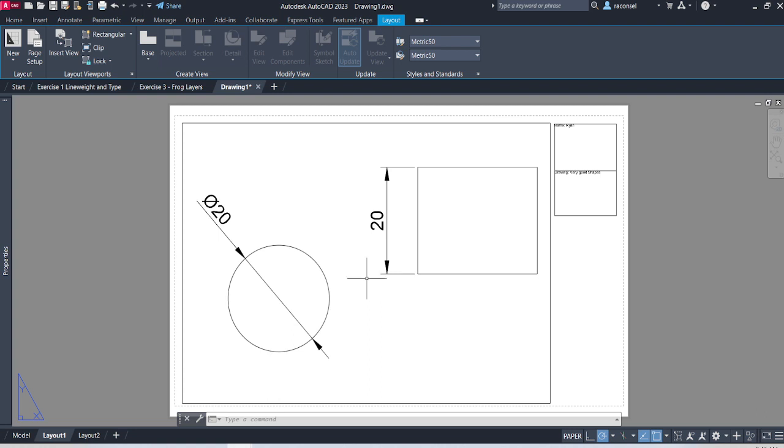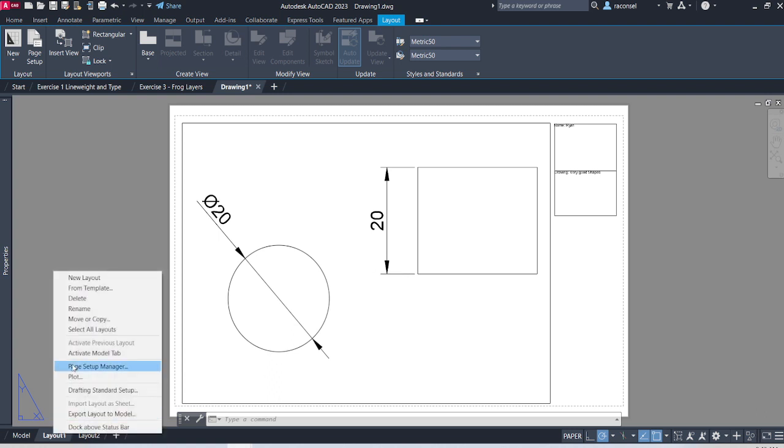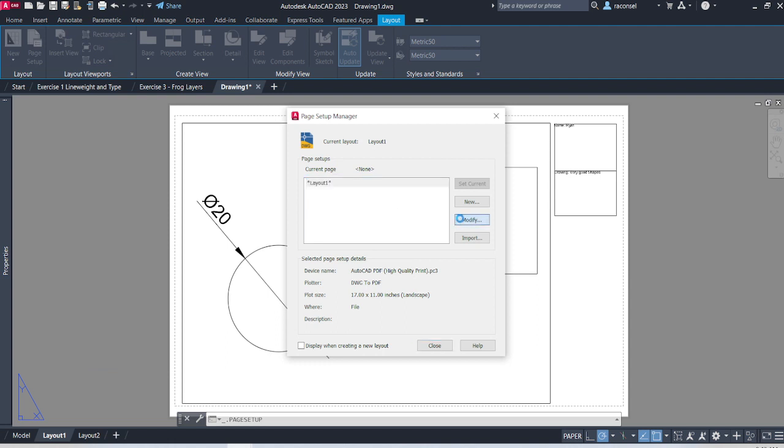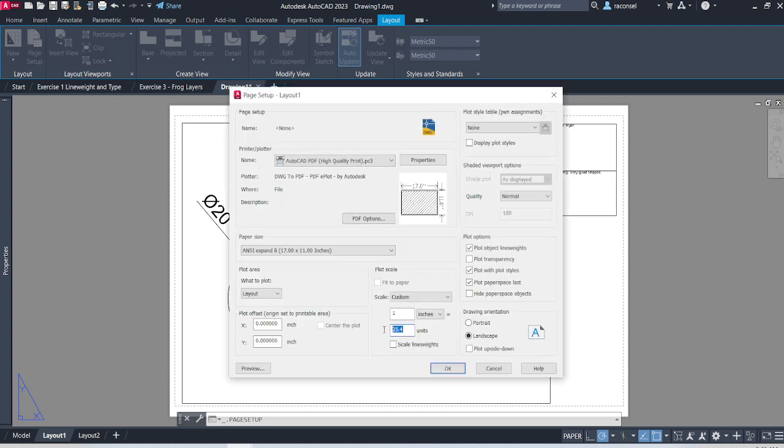This is where AutoCAD finally cares what units you're using. In my layout, one of the options in my Page Setup Manager was explaining what my AutoCAD units meant. So if I'm working in inches or millimeters, I can explain that and say, well, this right now is converting 25.4, let's flip to millimeters. This is saying 1 millimeter is equal to 1 inch. That's what I drew it. This is where I explain that.